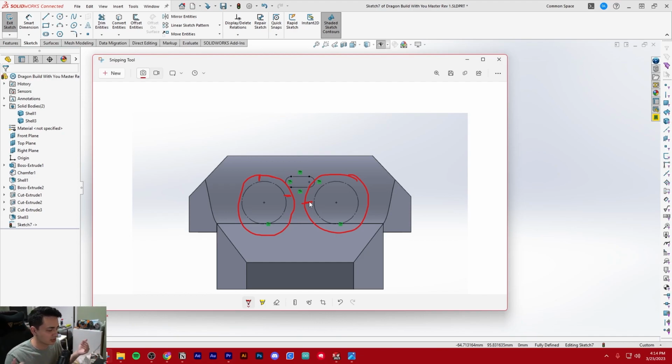Also, another reason for this is we can tell the software exactly what we want, but the printer in reality, whenever we go to print this thing, is not going to print exactly what we want, and that's called tolerance. Basically, our printers aren't perfect. You can tell it theoretically exactly where you want it to put material, but it's not going to put it exactly there, and that depends on your machine settings, how finely tuned it is. There are all different sorts of variables that affect tolerance, but that's a lesson for another time.